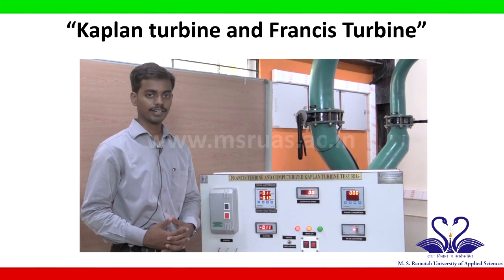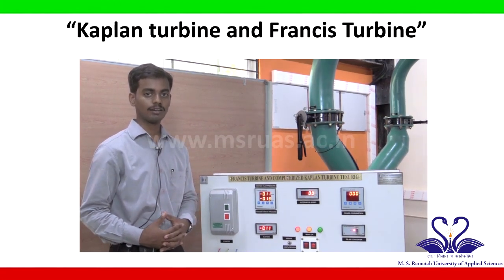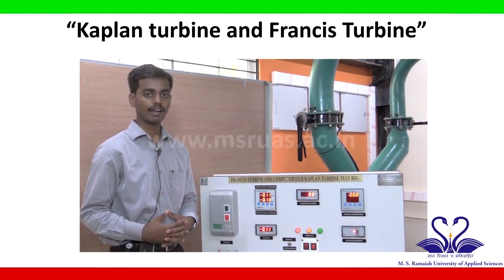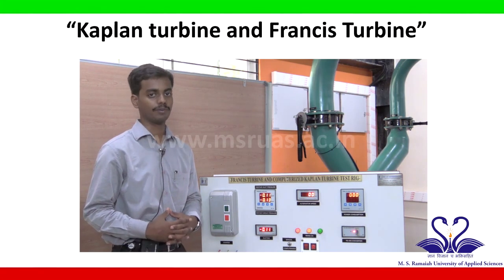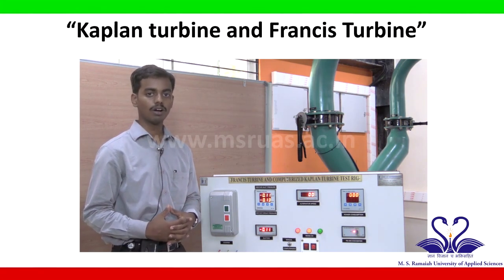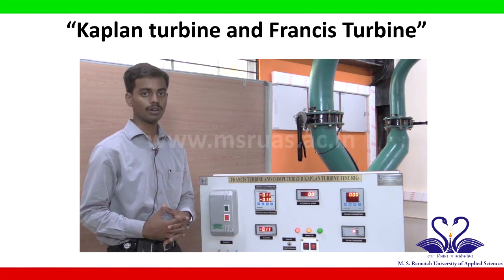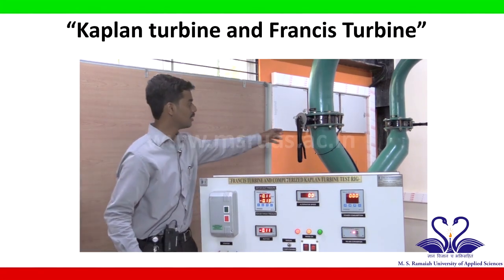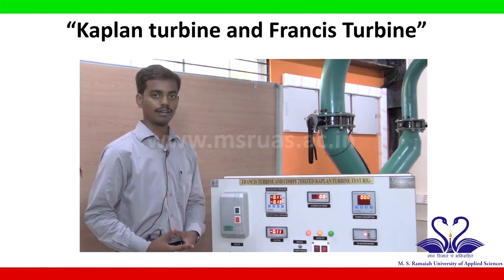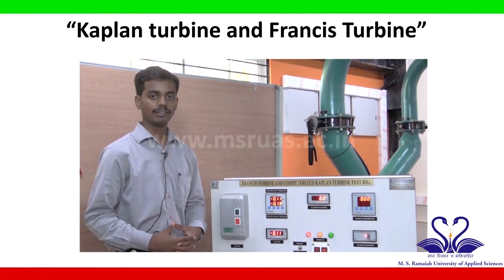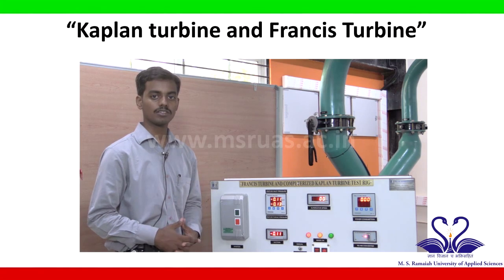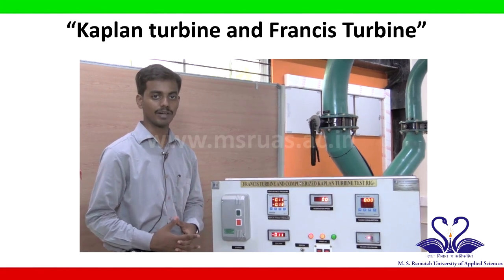We have conducted the experiment on the Kaplan turbine at constant head. Now the same experiment can be repeated at constant speed. The constant speed for the alternator can be controlled by operating the butterfly valve. Now we have conducted the experiment on both constant head as well as constant speed.